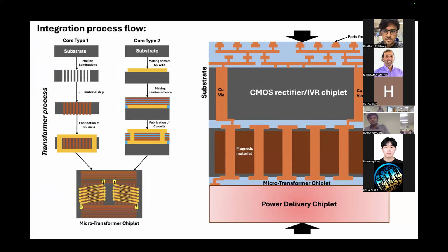But the only thing is the lamination part. You've got to figure that out. Lamination and also growth, because both are tough. This growth has to be done in the presence of a field, because you need to induce that crystalline anisotropy. So even if you're doing sputtering, it has to be done in situ. A lot of these people use setups where they have a whole evaporator sitting in a Helmholtz coil, essentially an MRI coil generating a very high magnetic field to create that kind of anisotropy.